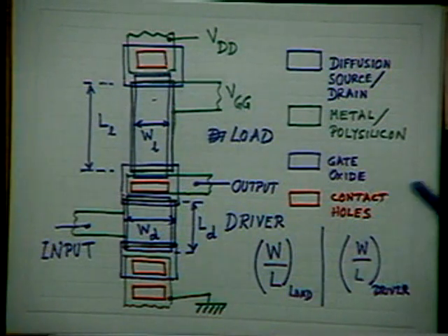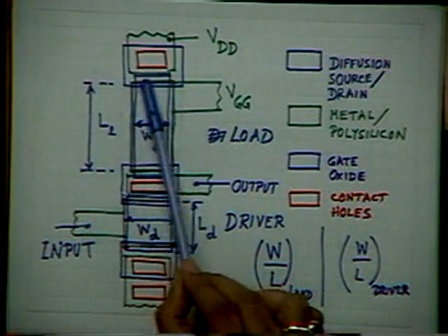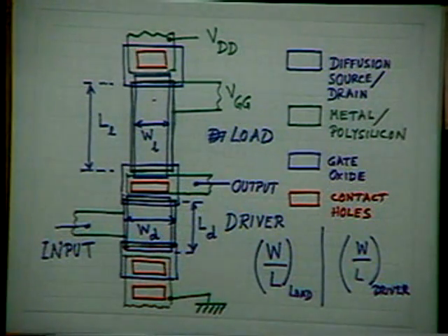And ultimately, it is also possible to have a transistor here which is a depletion mode device, not an enhancement mode device. I told you this is technologically more difficult, but that technological hurdle was removed, and the technology was first commercially successfully put forward by Intel. The name given to this technology was HMOS. I told you in the last class, HMOS means high performance nMOS technology. Now it has come, of course, to HCMOS, high performance CMOS, a different thing, we shall discuss it afterward, okay?